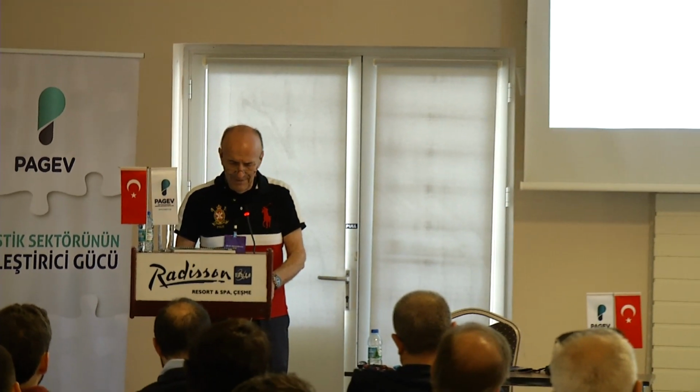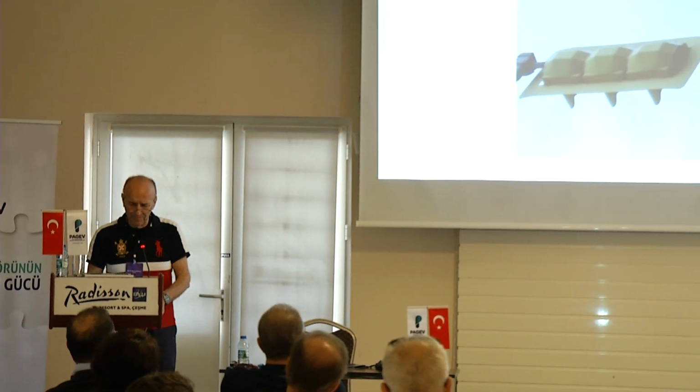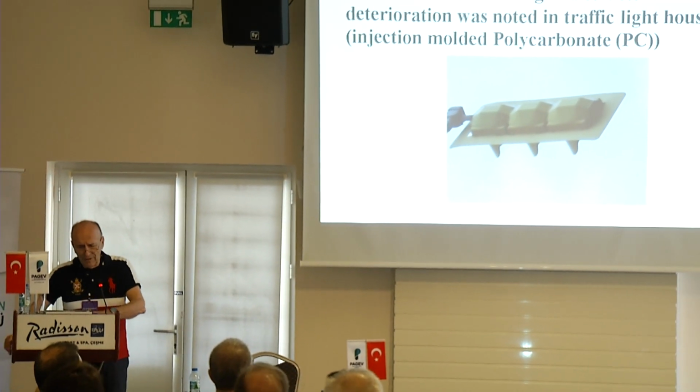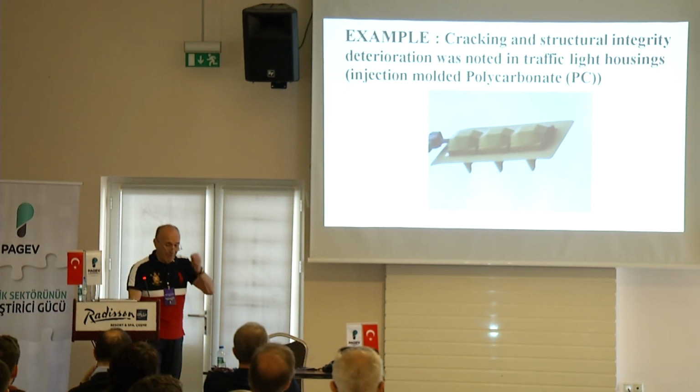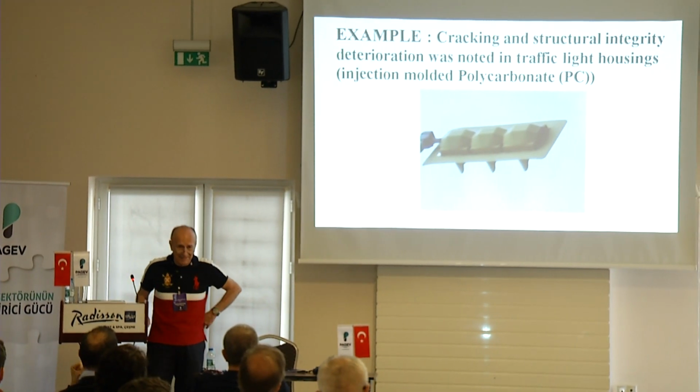You will see there what it means. You can get one low load melt index. You can get a high load melt index. From the two, you can approximate almost a viscosity. It's not very accurate, but you can approximate. With melt index only, did I solve a problem? Yes, I did.